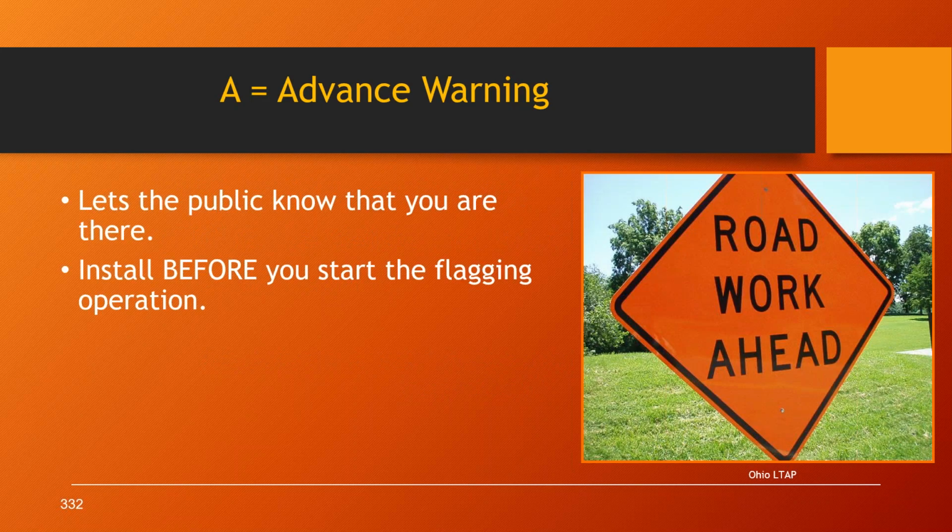So let's talk about the advance warning area. This is where we let the public know that you are there. So we need to install the advance warning area before you start the flagging operation.